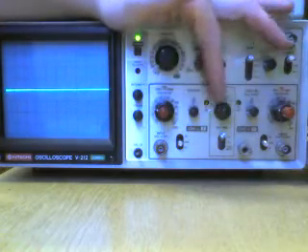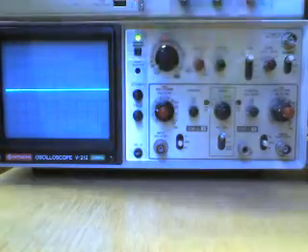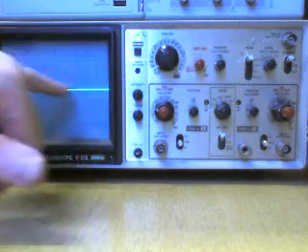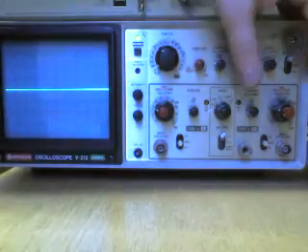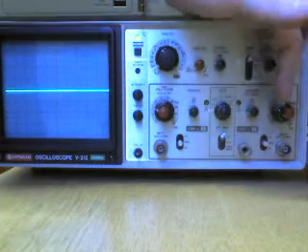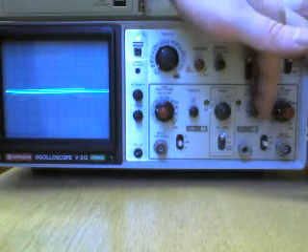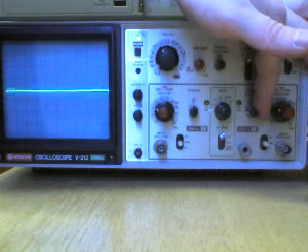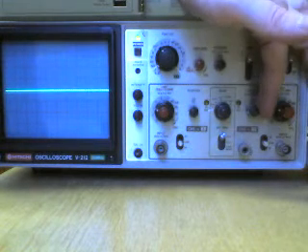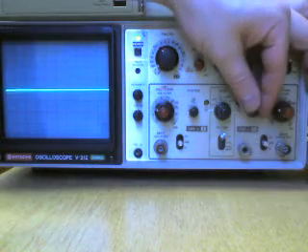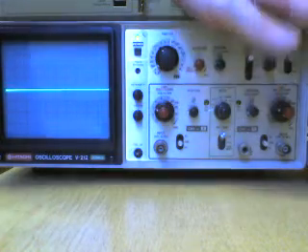So let's say for channel 1, we've got our control here set to channel 1. Channel 1 is set to 0 around the centre of the screen. Change it to channel 2, and we can move our channel 2 up and down until it's more or less in the centre of the screen. And there we have it. And that's our first little setup done.